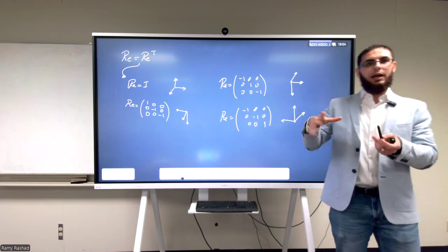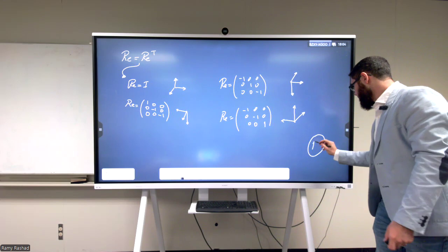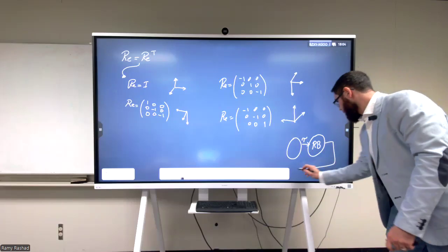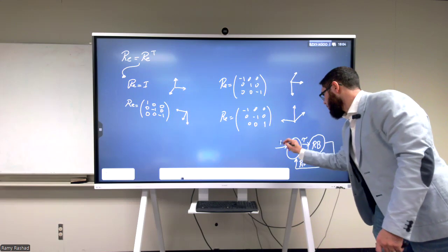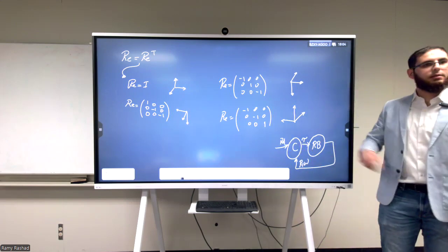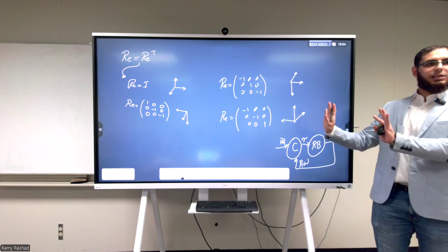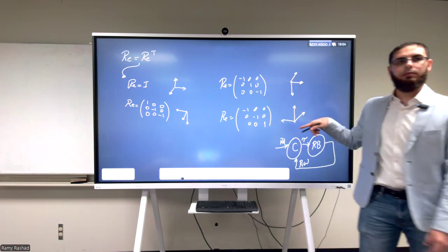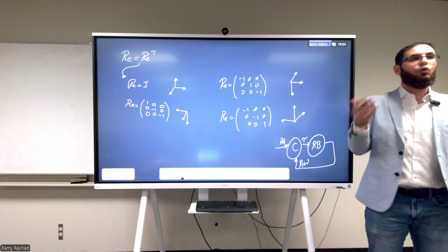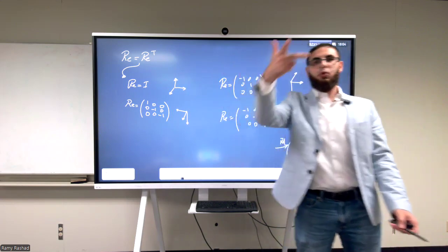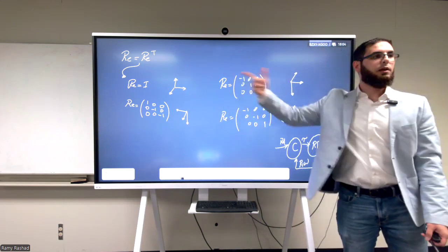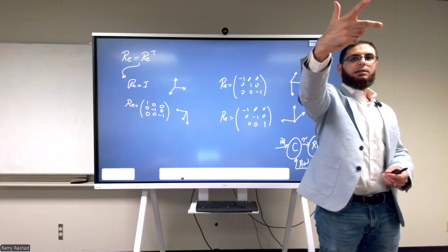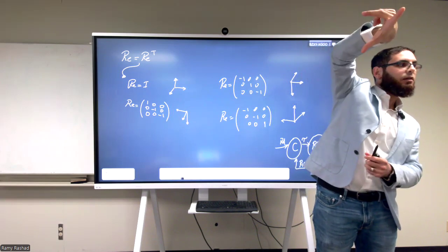If you initialize the controller, so now we have a controller. So we have the rigid body, and we have the torques, and I have a controller that will take the R and the omega, and will take some R desired, and will make this system asymptotically stable. We haven't shown that yet. It's the next step. If R_D transpose R is one of these four, you're going to get a torque of 0. So it will not do anything. So this one is what we want. So if I'm already R equal to R desired, I should get this one. But if R_D transpose R is equal to this matrix, it means that if this is the desired rotation matrix, and I rotated 180 degrees, and I initialize from here, I don't do anything.